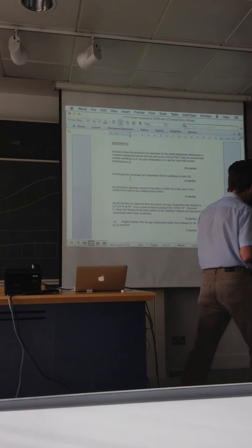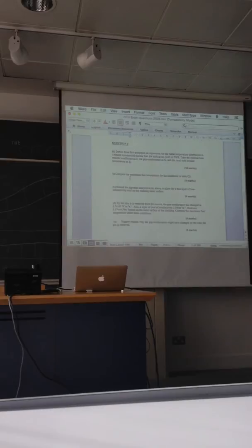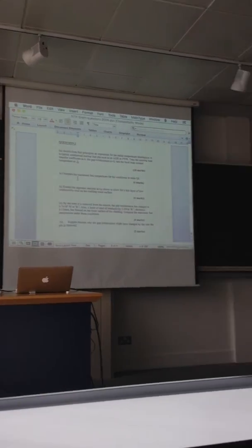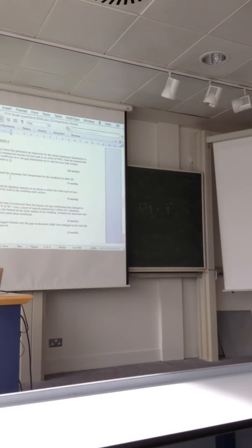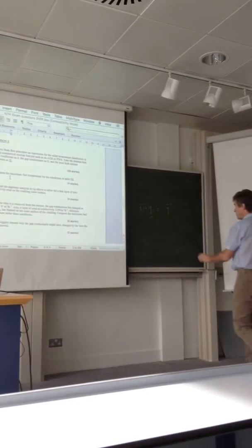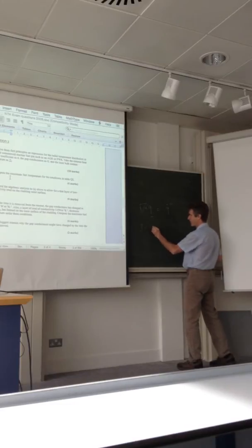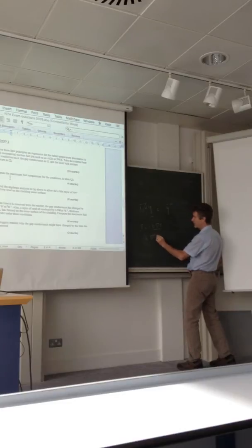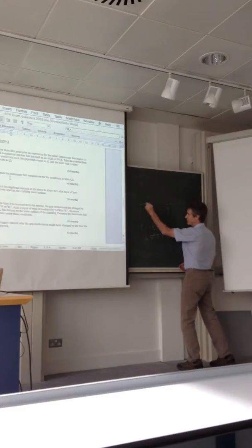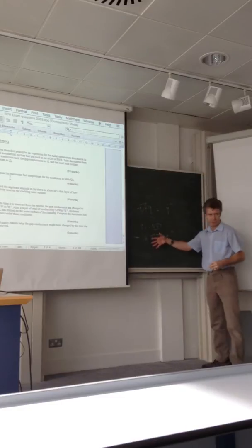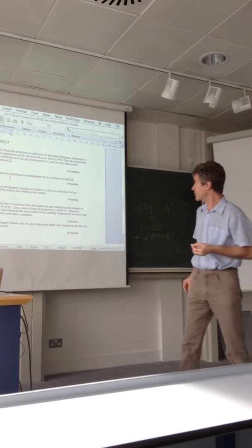So that would be our statement, and then that just becomes an equation, of course, because we need a constitutive law. We'd have a rho Cp dT by dt, so we've got temperature and heat flow, so we'd introduce a constitutive law to get rid of one of those, and that, of course, is Fourier's law. Q is K grad T. So we come up with a K del squared T. I'll probably drop a sign somewhere, but not too fussed. Okay, so those two together would give us the differential equation that we would solve.